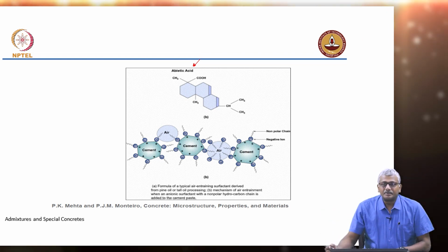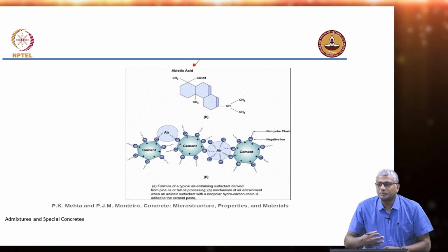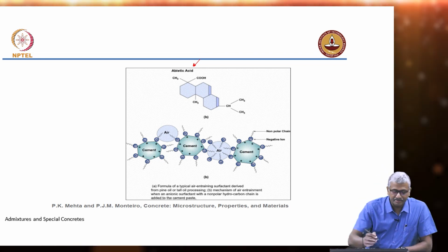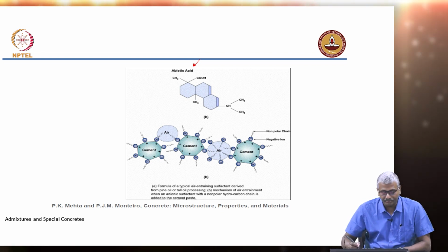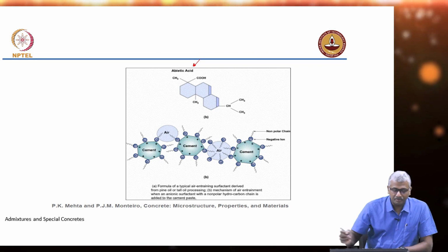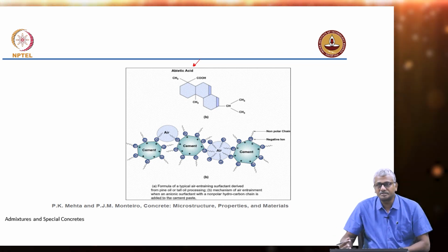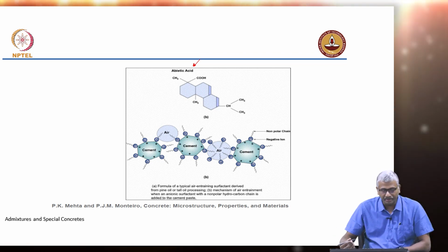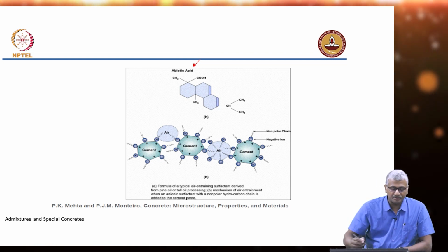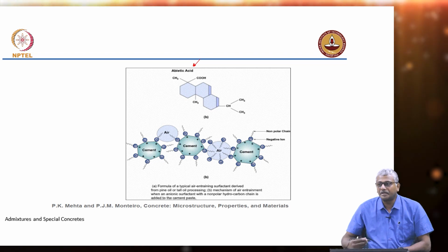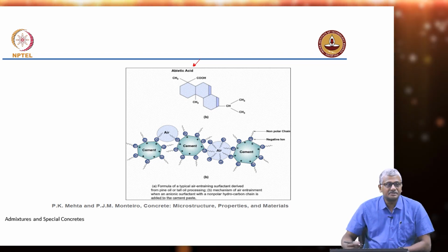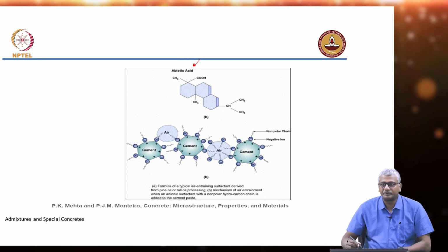Yeah, so in terms of composition, cement is composed of a few major oxides like calcium oxide, silicon dioxide, aluminum oxide and iron oxide. As you can see, the primary composition of cement is in terms of lime or calcium oxide. We have nearly 2/3 of cement composed of calcium oxide. Apart from these 4 major oxides, you can also have significant quantities of magnesium oxide, depending upon the source of your limestone, of course. And there are alkalis present to the tune of about 0.3 to 1%.